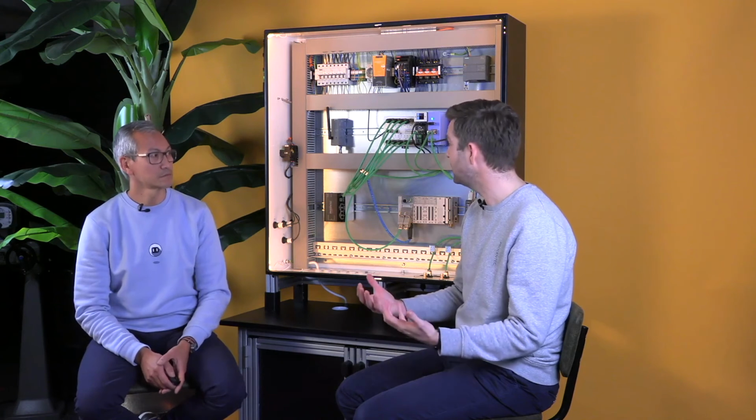Passive diagnostics is so important because we can go more into the timing aspects of the communication, and also we can go more into the protocol specific part of the communication. Bus loads and port loads are Ethernet in general, but if you look at cycle times or alarms, these are more protocol specific. Okay, so you need that data to see if it's actually protocol compliant or adhering to the protocol rules. Yeah, so you dive a little bit more into the communication itself. Okay, that's really interesting to know.